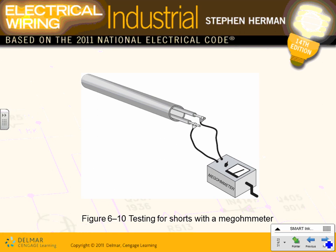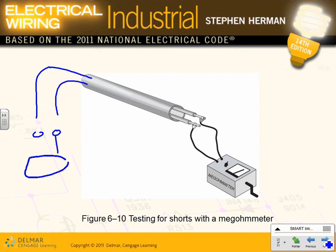The first thing you do on this side, guys, if there's a machine here, here's my machine, right? The first thing you do, Jeff, is you disconnect the conductor. On the other end, you disconnect the conductor too. Very, very important. Then you come over here and crank that one. You're sending current right through here. It shouldn't come back because it's not shorted, right? And you measure it back here.